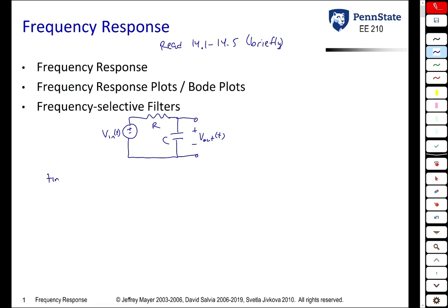So up until now, we've looked at everything in what we call the time domain. So plotting wise, in the time domain, your x-axis is time, your y-axis is whatever you're looking for, in this case Vout. Suppose, for example, the input was a unit step function turning off at time 0. So maybe your input looked like that. The corresponding output would be what? Well, you'd be in DC steady state here, and then once the input turns off, the capacitor would start discharging and eventually go to 0.